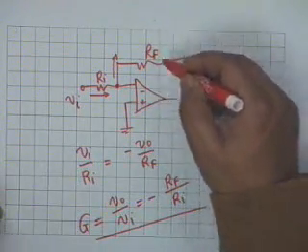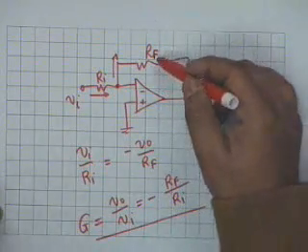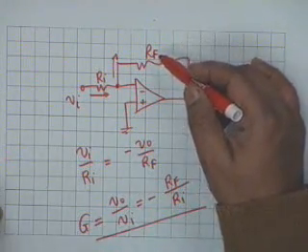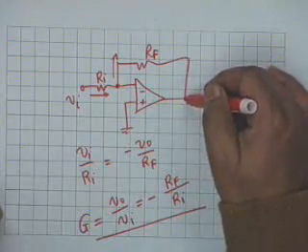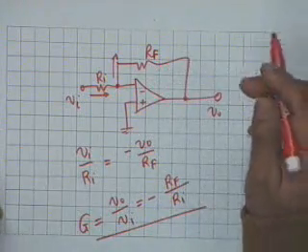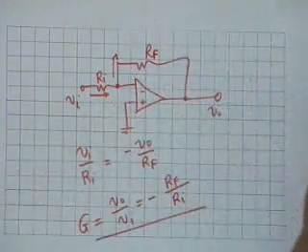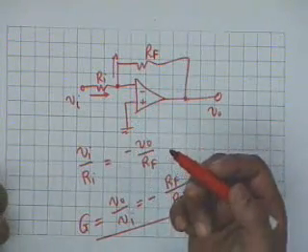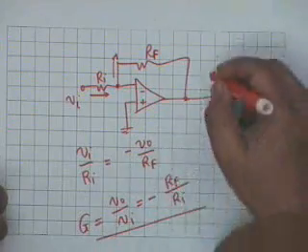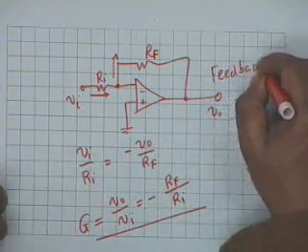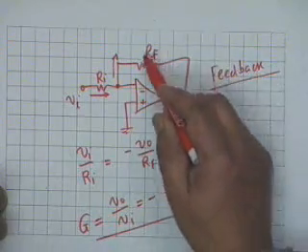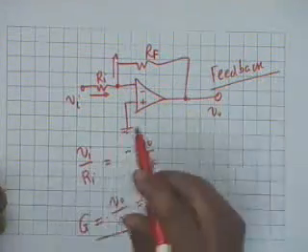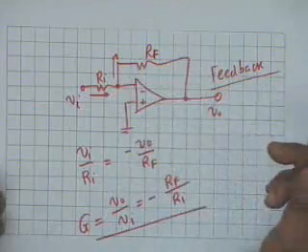The significance of the subscript should now be obvious to you. Capital F stands for feedback. That is, feedback is the path provided from output to input. From input to output is feed forward. Now if something comes back, you see something comes back through this resistance, a current, it is called a feedback resistor. We shall understand the meaning of feedback in much greater detail later on. But as this is the feedback resistor, and Ri, this subscript I stands for input resistor. Alright, so it is a ratio of two resistors only.